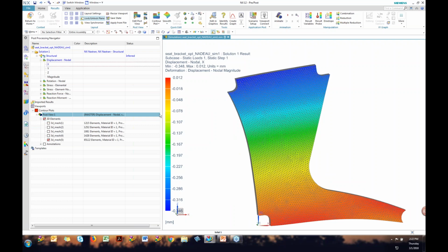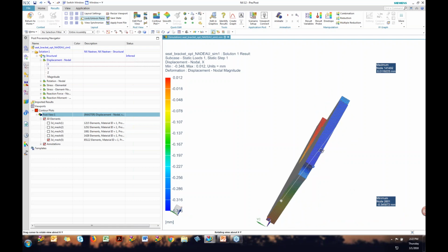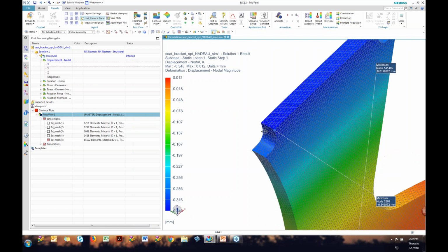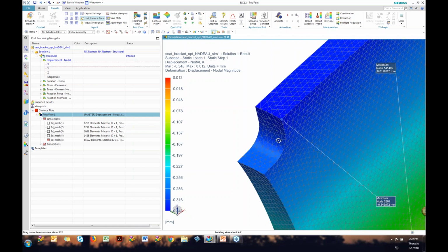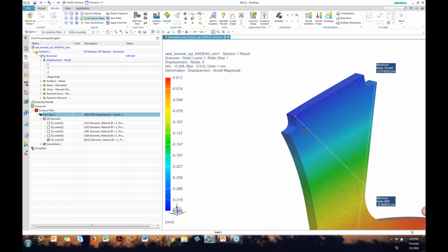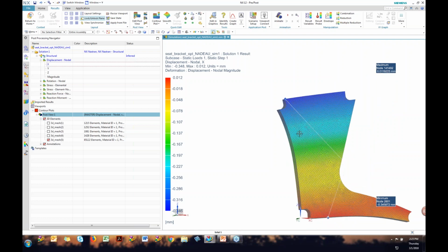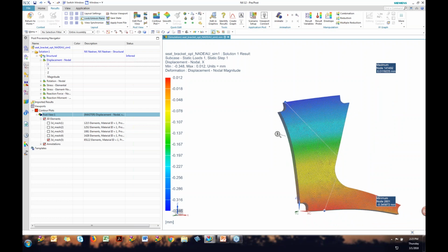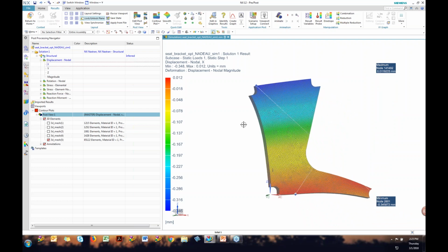Maybe we're interested in all this design space and we want to look at it, put annotations and see, oh, this location right here has a maximum of 0.35 millimeters. But maybe my regulation is that this thing can actually move three-quarters of a millimeter before something happens. So maybe when I optimize it, I'll say, hey, you can move all the way out here, and that's fine. You still meet my design criteria. So that's one of the nice things that you can do with optimization.